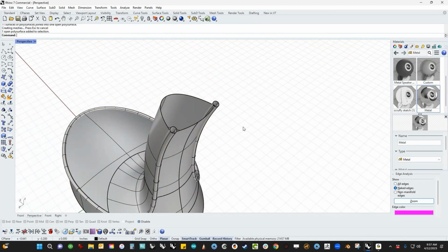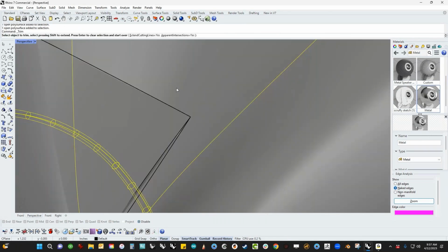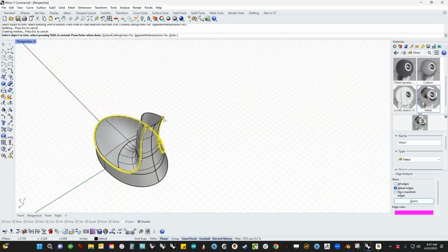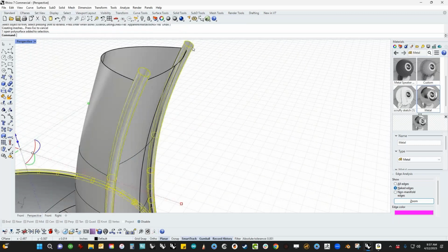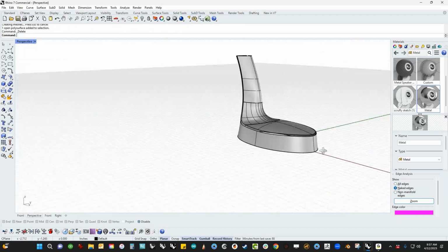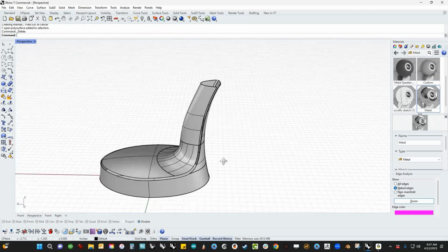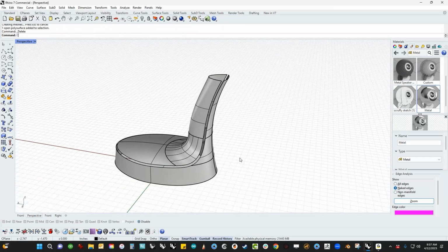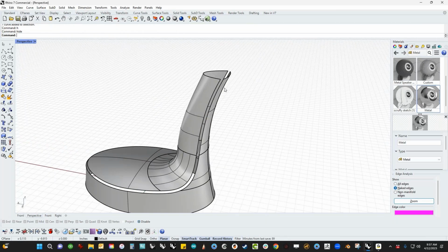And this is really cool because what it does is it builds perfect little gaps. I can click in here, and when I delete this, you'll see, it builds a perfect little gap around this thing. And if you've seen any of my other videos, you will have heard me harp on this. But sometimes it's as important to build specific gaps as it is to build specific surfaces. You just kind of have to flip your thinking. And in this case, we wanted a specific gap that we can then go back and fill with blend surf.